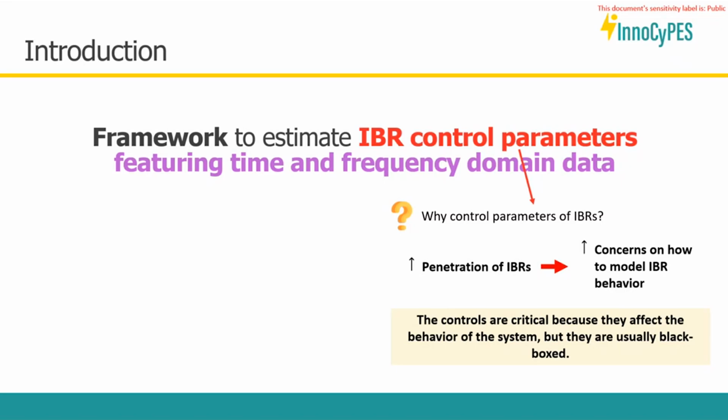But with IBR controls, most OEM models are not provided by the manufacturer because it's proprietary information for them. So some of the methods that we use for the synchronous generator, we cannot just extend to the IBR. Now we have a different challenge, and the main thing is that they are black boxed. You have different ways that you can model the control, and we have a demand for models that are a bit more generic. I will talk a little bit more about this.